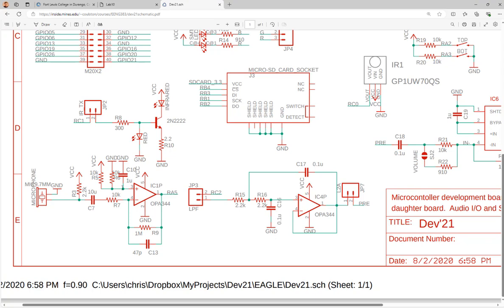It's an 8 bits ADC. So anyway, the audio signal comes in to the Mac, and the Mac is connected to the first order low pass filter, and this pin doesn't have a header pin, so it's directly, physically shorted to the RA5 pin of the microcontroller, which is connected to one of the ADC channels. Which channel? AN4, right? Keep in mind, when you are doing the ADC configuration, change it to AN4 in the ADC register. Otherwise, you are reading zeros. Sometimes you are reading 23s. They're just some floating charges accumulated on the pin. But it's just basically zero, nothing, okay?